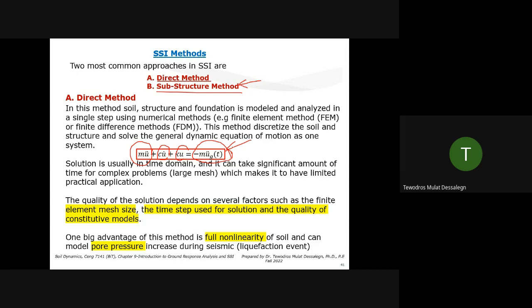And it's so time taking. The solution is usually in time domain and it can take a significant amount of time for complex problems, large meshing, so many finite elements, which gives it limited application for practical cases. The quality of the solution depends on several factors such as finite element mesh size, the time step you're using for the solution, and the quality of the constitutive models.